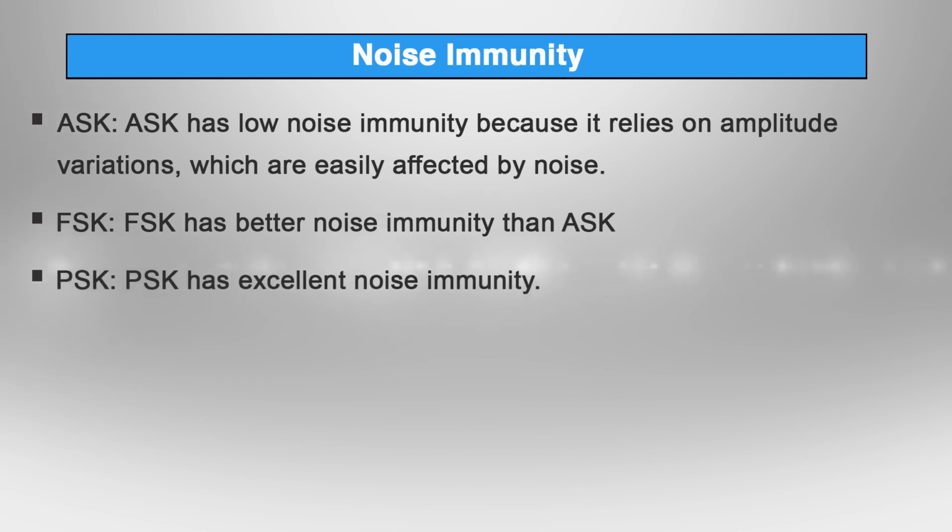In PSK, noise immunity is high due to its reliance on phase variations. The technique is less affected by amplitude noise and is more robust in challenging conditions. PSK is well suited for environments where noise is a concern, such as in satellite communication and high speed data transmission.